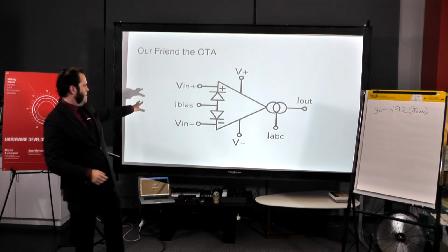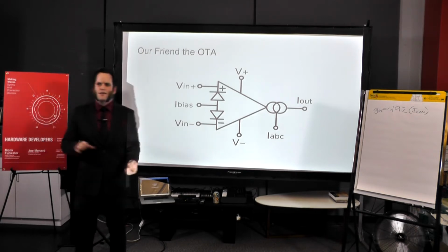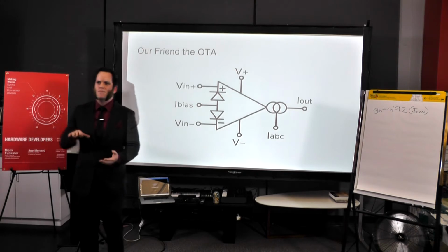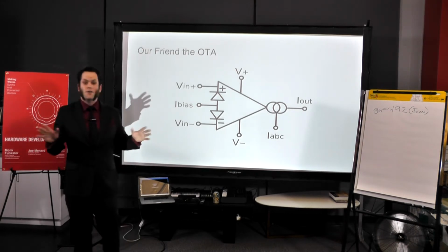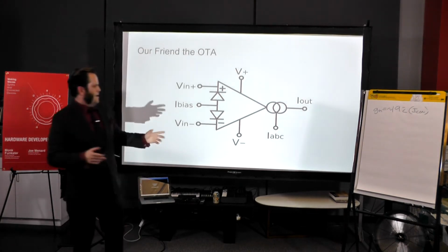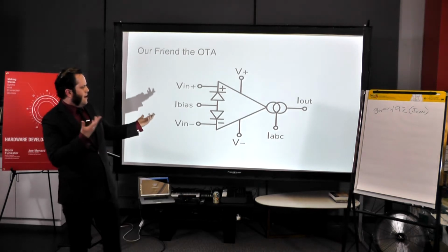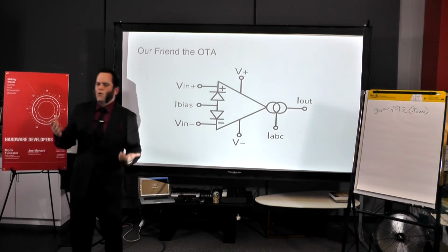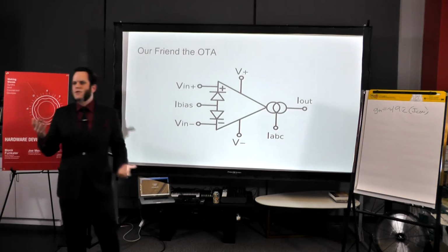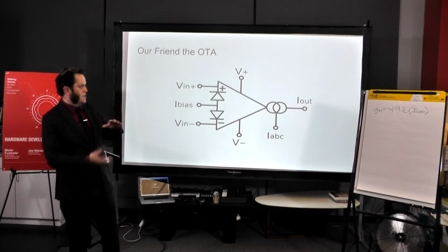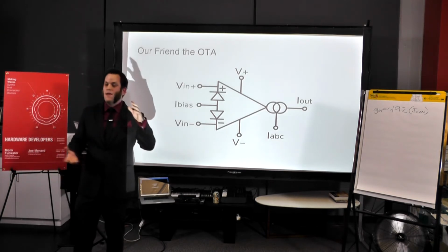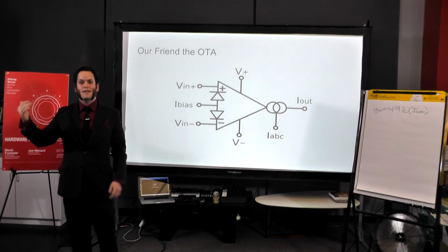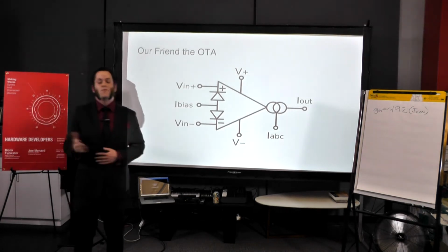And some of the newer ones have this I-bias pin that you can kind of extend that good linear input range up to like 30, maybe 35 millivolts. I know, it's amazing. And then, your I control current input range is anywhere from like 0.5 microamps to 500 microamps. It's a pretty wide range, and that gives us a cool 1 to 1,000 range. If we're trying to cover 20 hertz to 20 kilohertz, that's a 1 to 1,000 range. It works out pretty well.